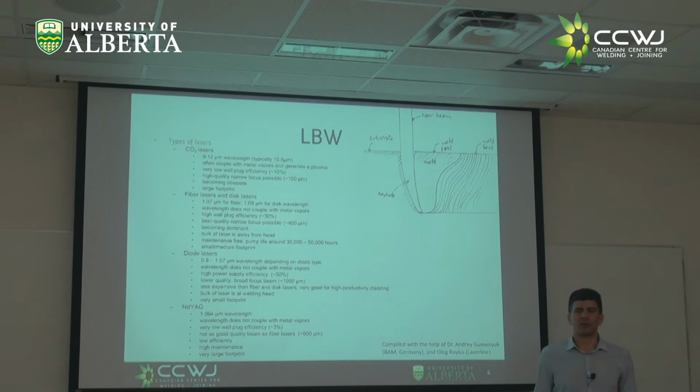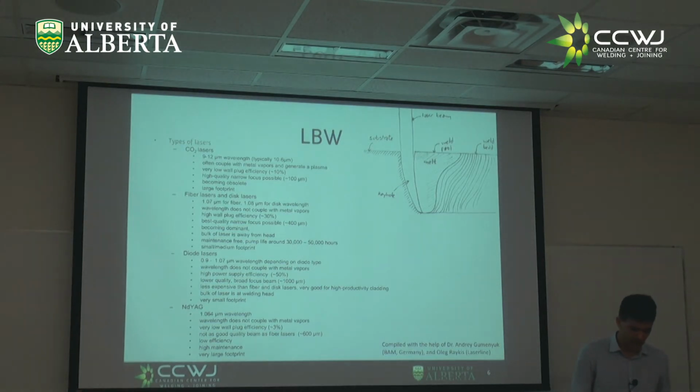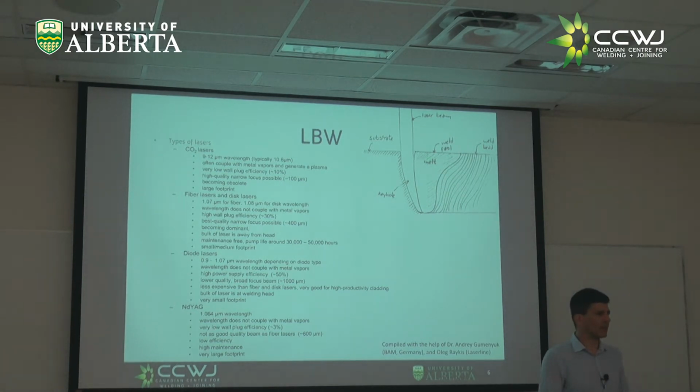However, this wavelength matters because, for reasons of the physics that I don't understand yet, somehow I hope someday somebody will explain them to me, the reflectivity of the material depends on the wavelength of the light. And the reflectivity at 10 microns is much higher than the reflectivity at 1 micron. So coupling a CO2 laser is very difficult because it bounces much more light than a diode laser or a fiber laser, right? That's one thing.